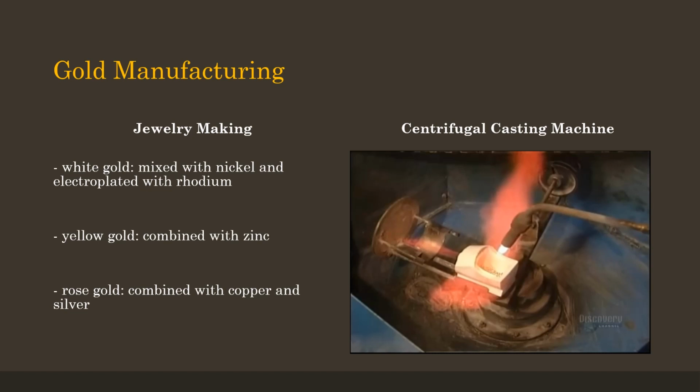The plaster container is first placed into the end of the centrifugal arm, where the open channel is faced towards the pouring bin. The molten metal is then poured into the bin and the machine spins so that the molten metal is forced into the ring mold.